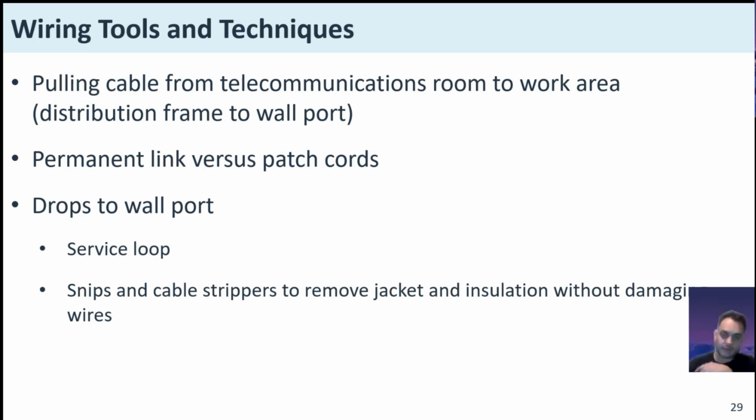Same thing for coaxial and other tools. Cable cutting blades should be rounded to preserve the wire geometry. Cable stripping tools should have the correct diameter to score a cable jacket without damaging the insulation wires. Heavy-duty cutters are required for armored cable.